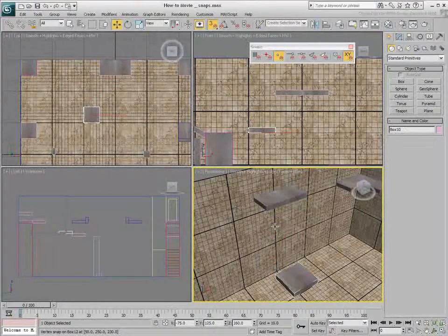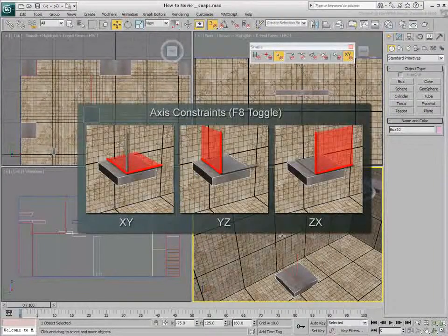It is important to note that this mode also works in two directions simultaneously. This in effect replaces the 2.5D mode you learned about earlier. To set this mode to work in two axes simultaneously, use F8 to move between the XY, YZ, and XZ planes.